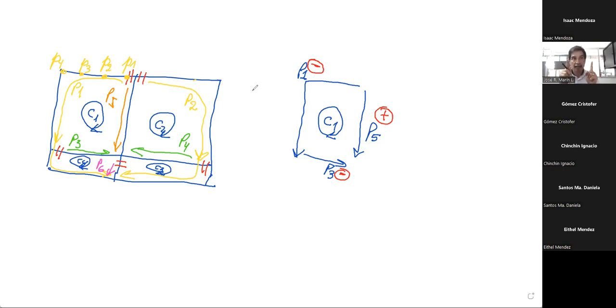But remember that we also have a Q2 in cell 2, and we have Q4 on cell 4. And those shear flows are going to influence the distribution of the shear flow of the cell 1, because these two cells are adjacent to the cell 1 which we are analyzing. Okay? So we still need a little bit more information.